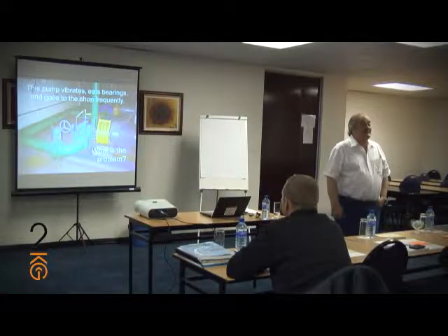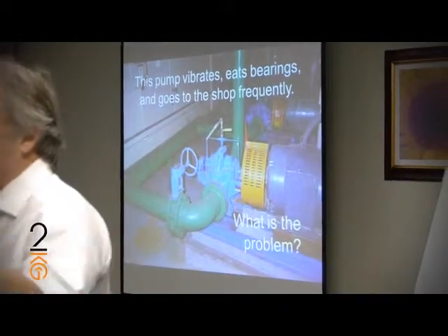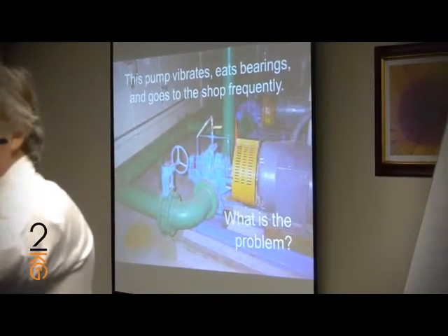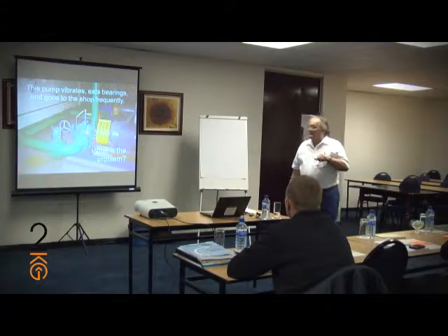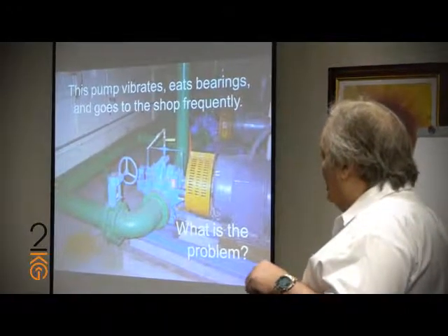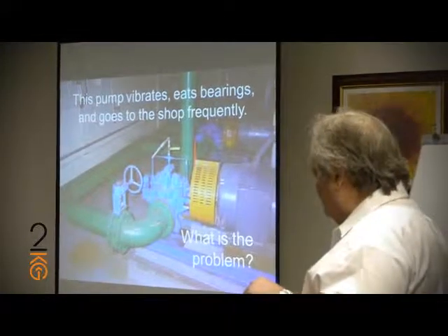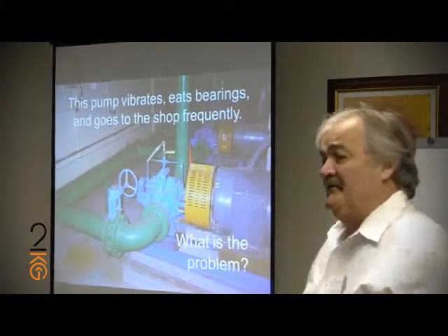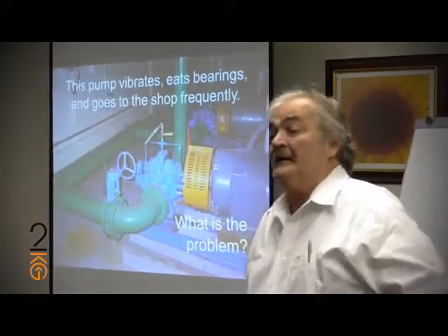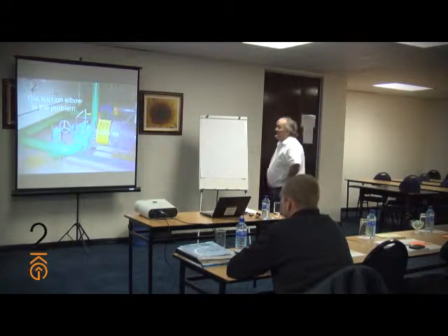See, the process engineers thought they had a bearing problem. What's the problem with this pump? It's looking at you. This is your big problem right here. You do not put an elbow, especially a right elbow, on the suction nozzle of a split case pump or any other pump. So the suction elbow is the problem.